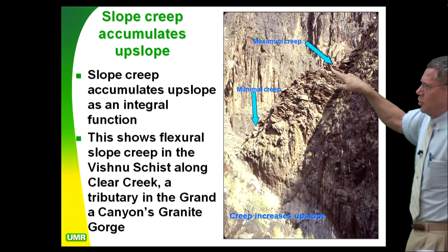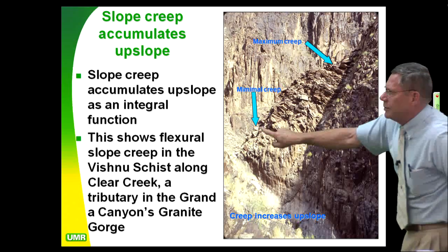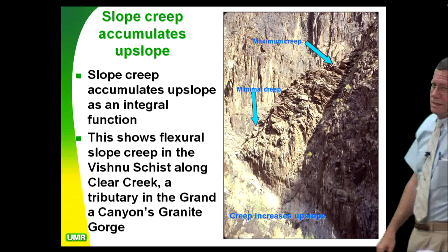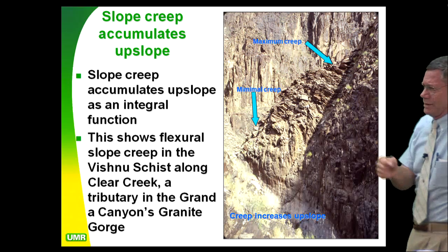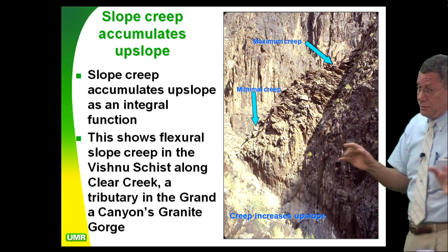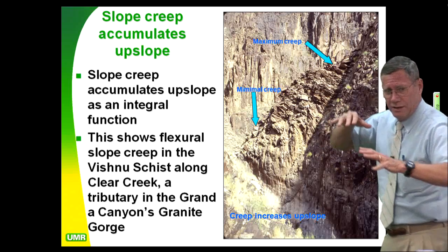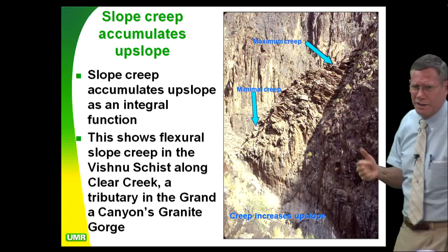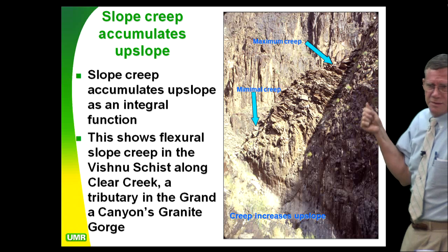Now, if I put a slope inclinometer right here, and I put one right here, and I put one right there, I'm going to get 3 different answers. 22 years ago, I went to China for the first time. They were putting inclinometers in there, and they said, oh, Dr. Roger, we want to show you, we got these slopes, and some parts of the slope are moving a lot, the other parts not moving so much, always the upper part moving more. Well, the upper part's moving more. It's the same darn slide. It's the integration of strain upslope.